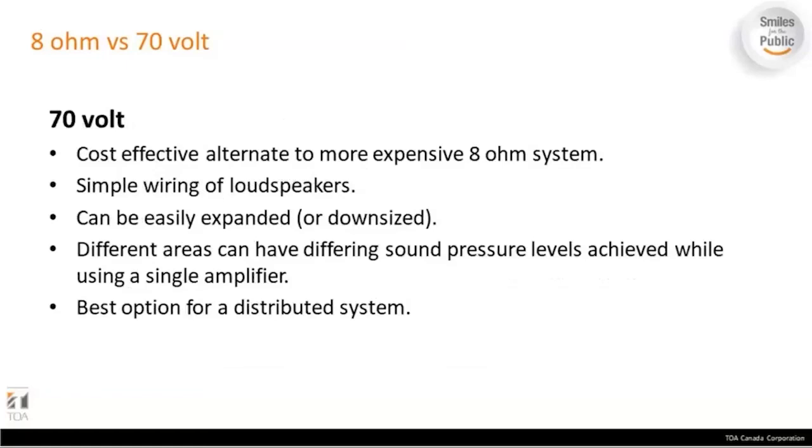Now, a 70 volt system is usually a cost-effective alternative to the much more expensive 8 ohm or low impedance system. And the wiring is pretty simple. You don't have any confusion of series or paralleling speakers, right? And it can be easily expanded.